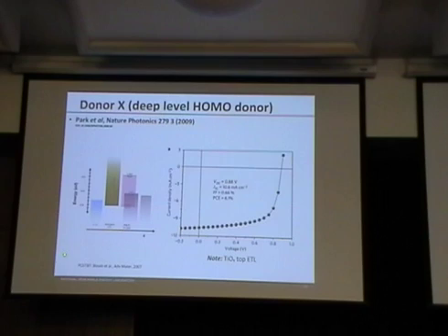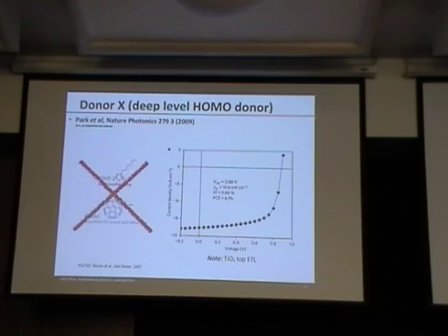Moreover, because the oxide is a nice semiconducting system where I have some tunability, when I go to something that's not P3HT, I should be able to match up the appropriate contact properties to improve the overall device performance.